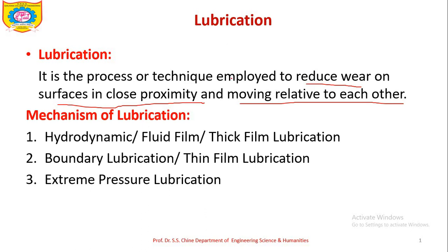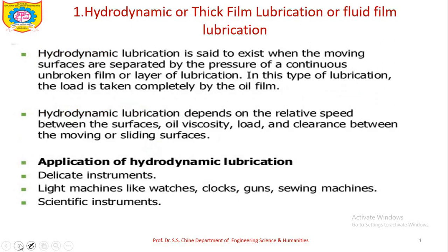This lubrication is of three types, or there are three mechanisms of lubrication. The first one is known as hydrodynamic, which is also known as fluid film or thick film lubrication. The second one is boundary lubrication, which is also known as thin film lubrication. And the third one is extreme pressure lubrication. So let me start with the first type of lubrication mechanism, that is hydrodynamic or